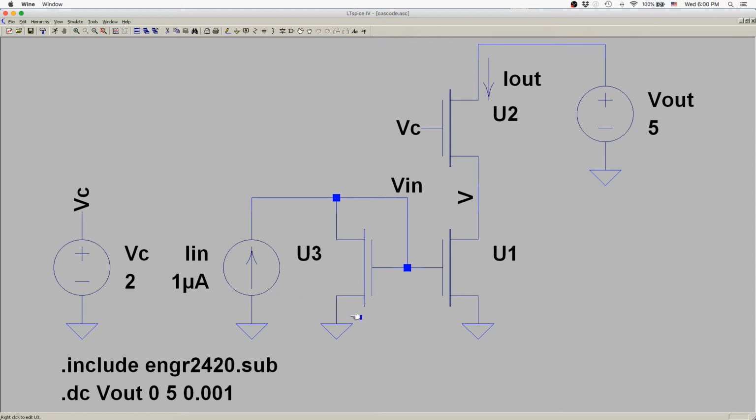we have a way of generating a gate voltage that's appropriate to make a transistor pass a given amount of current, and that's the diode connection. Right. So if we want to make, let's say, the nominal saturation current level in this branch here be 1 microamp, which is about the threshold current for these type of devices we've been working with, we force a microamp of current into a diode-connected transistor that's matched with the transistor we want to produce the microamp in, and we form a current mirror. Okay, this is not surprising at this point, hopefully.